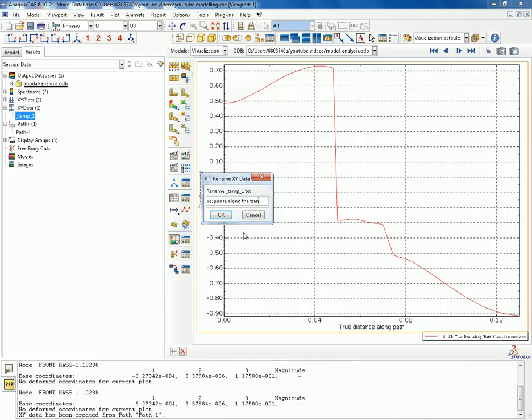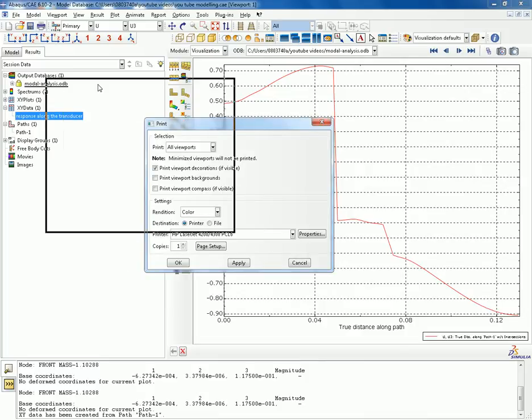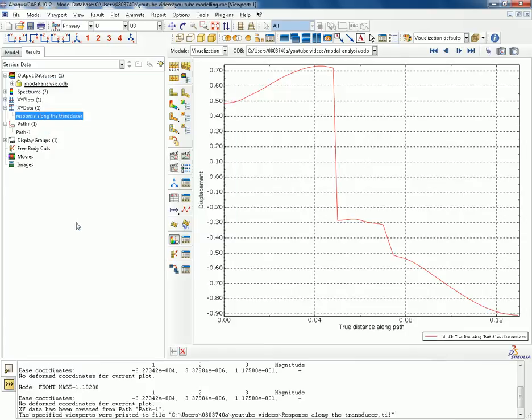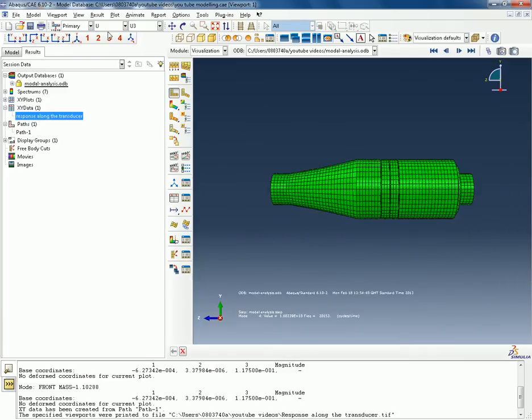So here we have to specify the range of frequencies we are interested in. As I've said before, I'm interested in the longitudinal mode. I've just created this shape to show you how we can get the harmonic response. So this will represent the frequency, and the Y should represent the amplitude. I'm interested in this mode of vibration, the longitudinal mode I've seen before, but I'm also going to extract the lower mode and the higher mode, to see how close they are to the mode of interest and how they can affect the performance of my transducer.